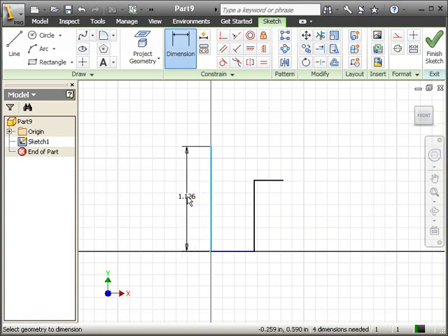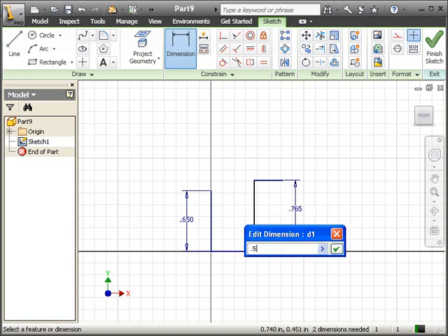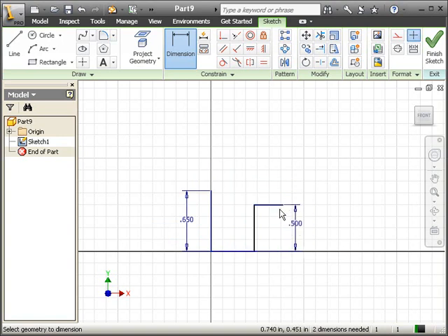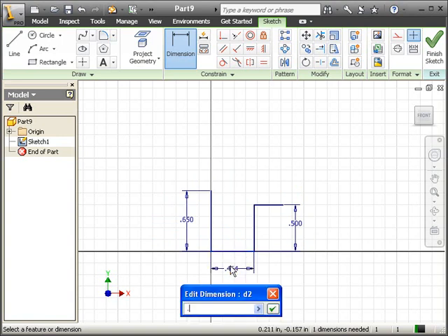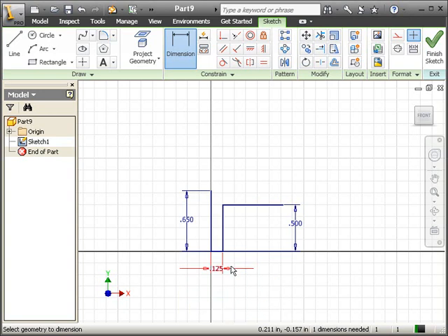The total height of this hitch peg is 0.65. The height from the bottom to the bottom curvature is 0.5. Okay. Now, before this is rotated, the bottom diameter of the peg is 0.25. So we need to get that 0.25 and divide it by 2 to give us the radius.